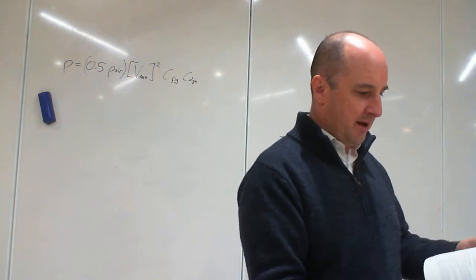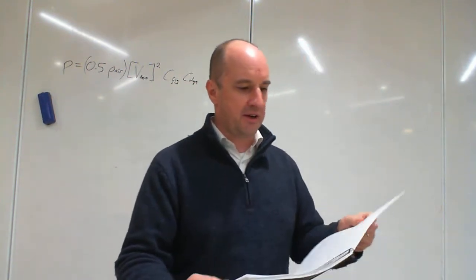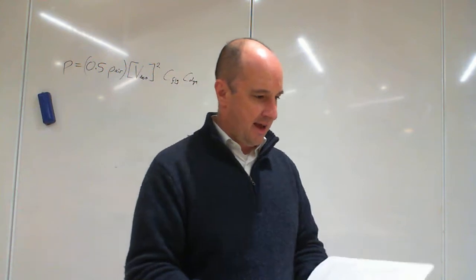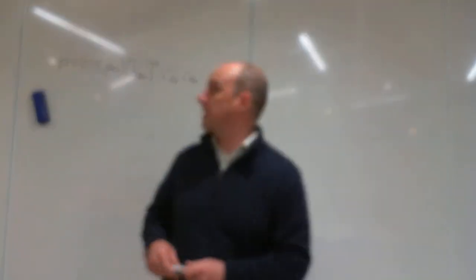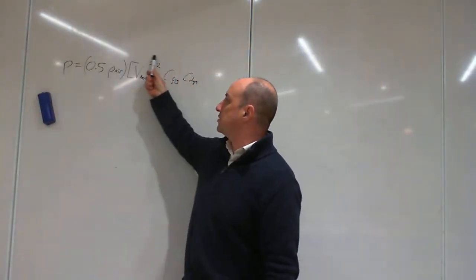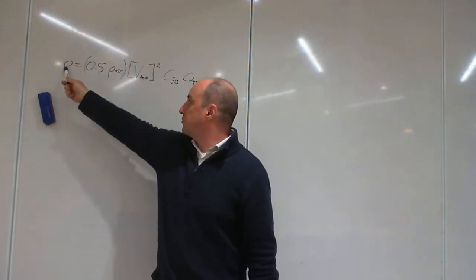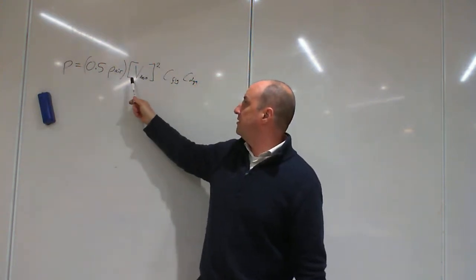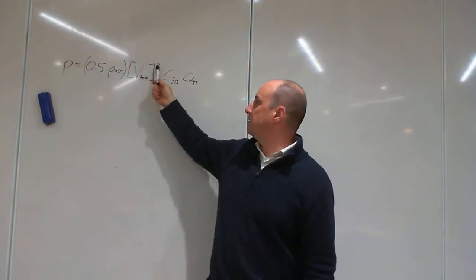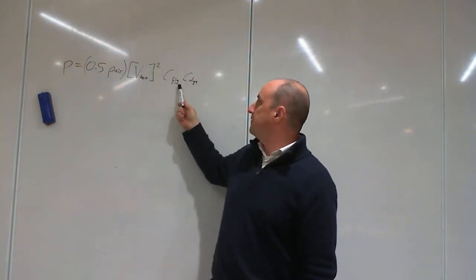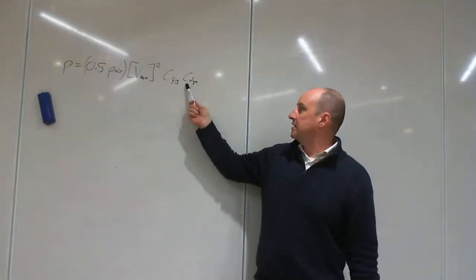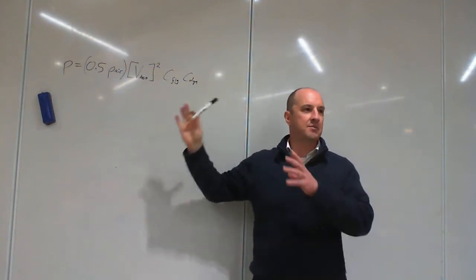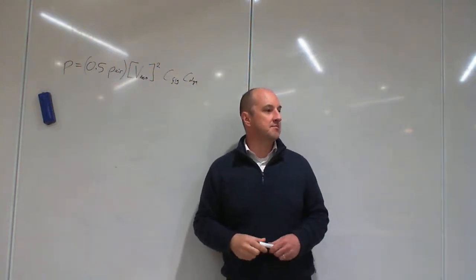So the first part is then to go to the calculations of the wind speed actions. And what we do is we talk about the site that we have and the wind speed. Now, when we get to that, this is the key equation which joins the two parts together. That's the pressure, that's the density of air, that's our wind speed squared, don't forget that. That's our C fig, which is all about the shape of the building or structure we're doing. And C dynamic, which is about how the thing interacts and moves with it.